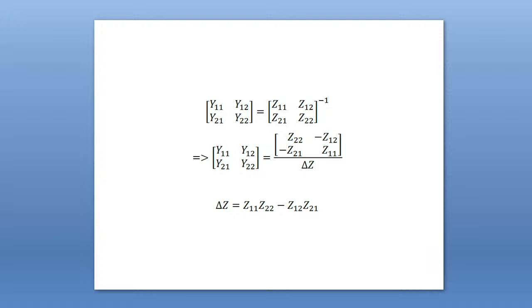Now you use the relationship between z and h parameter, use the values of the z parameters, and check the h parameter for the theoretical case. You compare it yourself, and you share your result after comparing theoretical values and experimental values.